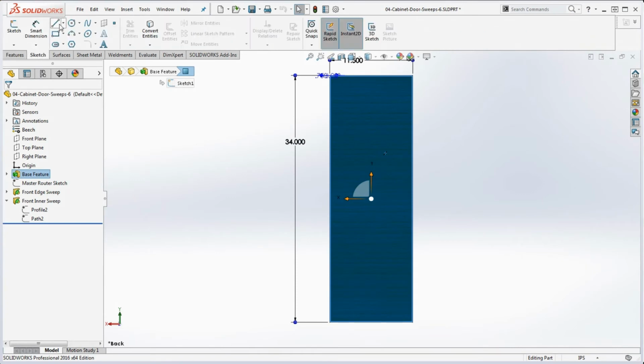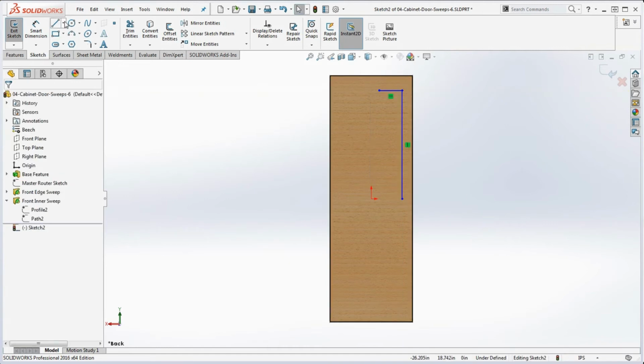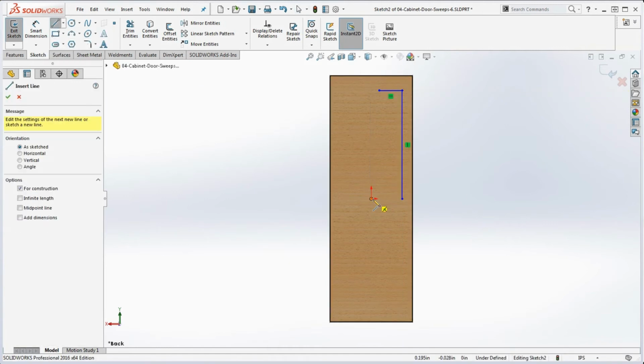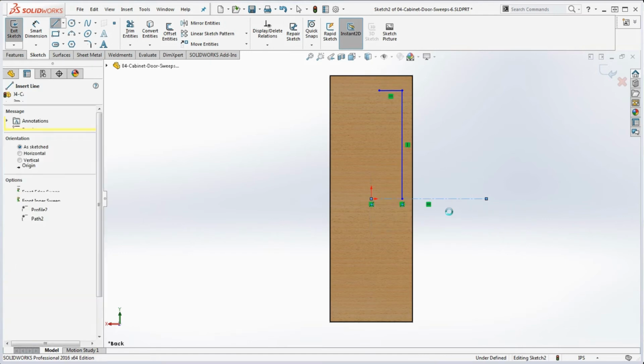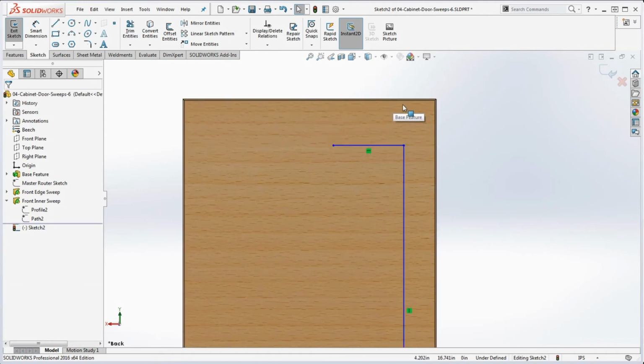So let's go ahead and start in the surface. Let's just go to sketch, and let's just sketch this thing out. When we brought that line down here, we might want to take a center line and maybe go from the origin out here and pick up that point if we can. So now we have a coincident relationship. We have it horizontal. We have a coincident with the origin down here. So now we have that in place.